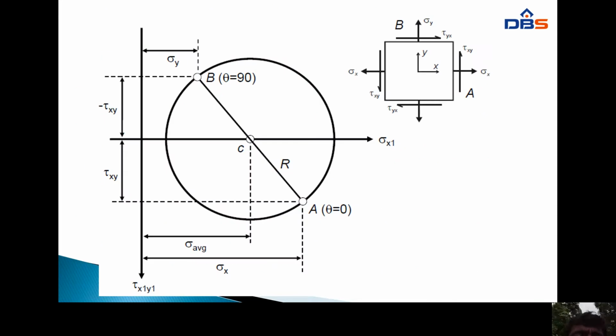Okay, this is the Mohr circle figure. Now, the above figure is a plane truss problem. Okay, plane truss, the stresses are acting on the plane at theta angles. In this figure, the stresses are acting on the 2 theta. First of all, we can draw the x-axis and y-axis, and the x-axis you take in the positive direction. Some point C is the center point of the circle. We can take some point and radius equal to r. We can draw a small circle.